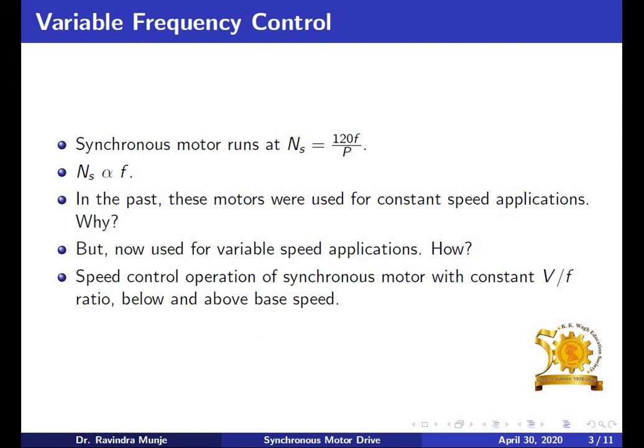Whereas for speed control above base speed, motor is operated at rated voltage and variable frequency. Here, pullout torque decreases with increase in frequency.